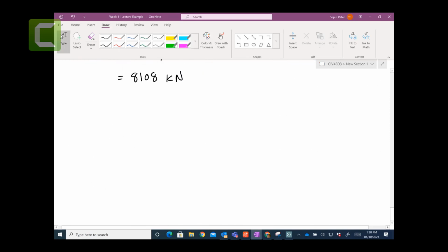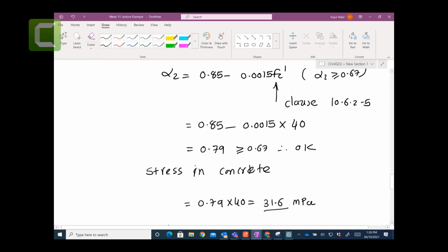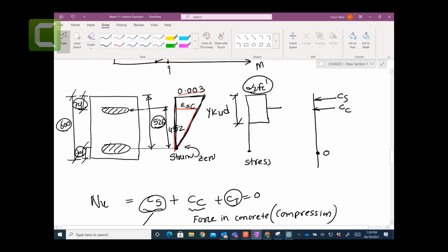Now to calculate the moments, we just need to use those diagrams. The moments that we're going to calculate, I think we have some room there or no? I think here you want to calculate. Now there is one term that I like to introduce, called plastic centroid. Now what is the plastic centroid? For the cross section, it is the point where, when you apply the load at that point, you don't have any bending.